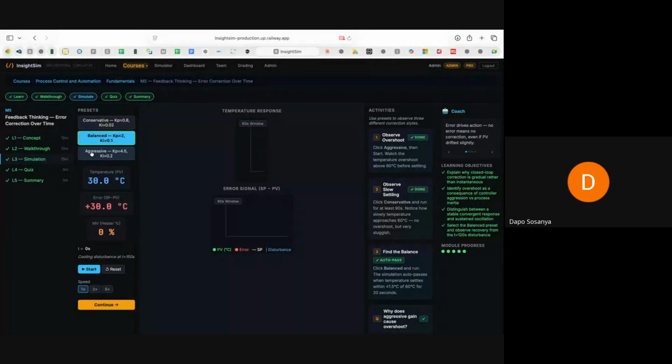And these are set by the process engineer or the control systems engineer. And these values are written into the PLC, just to provide that context. Those values are written into the PLC. These are the values you see on your HMI. So the process variable is presently at 30 degrees. The error, which is SP minus PV, is 30, right? That is, the process variable is much lower.